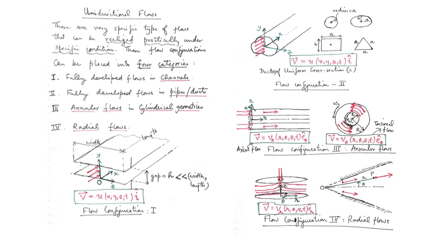I have shown it with two red vectors coming vertically downwards, and as it passes through the hole, it enters the gap region between the two circular discs, and gradually the streamlines tend to spread all around in the radial direction. Apart from a very small region near the entrance, the fluid paths appear to be very radial in nature.